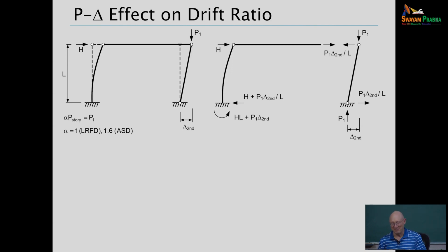But anyway, I'm digressing. So in the AISC specification, AISC likes to give no preference officially to one or the other. And so we handle things where if it's LRFD, they have a factor alpha. We can't use alpha critical in the American spec because we use alpha for something else. And that's equal to 1 in LRFD. It means we're at strength load level when we design by LRFD.